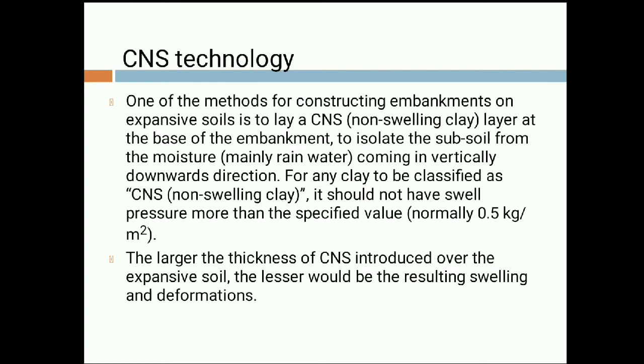CNS technology. One of the methods for constructing embankments on expansive soil is to lay a CNS layer. Now what is a CNS layer? A CNS layer is basically a non-swelling clay layer at the base of the embankment to isolate the subsoil from the moisture, mainly rainwater, coming in a vertically downward direction.